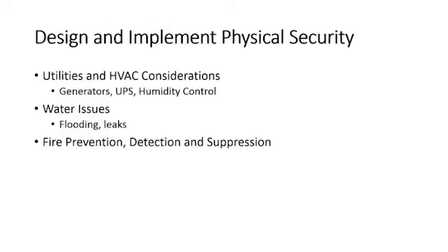What about utilities and HVAC considerations? Right? Most of the time, we've had UPSs for a while, an UPS, or an uninterruptible power supply. It's the battery pack sitting on the floor that if the power goes out, it will keep your server on or keep your workstation on or keep your laptop going until you can shut it down gracefully. It's not like it's going to run it all day and night. Depending on the UPS size, I guess I should say, most of the ones you get for your desktop servers will keep them going for 30 minutes, 45 minutes, an hour maybe. That allows you to get there and shut it down properly so you don't have data corruption and broken sessions and just bad things that could happen by just jerking the power out of your server.